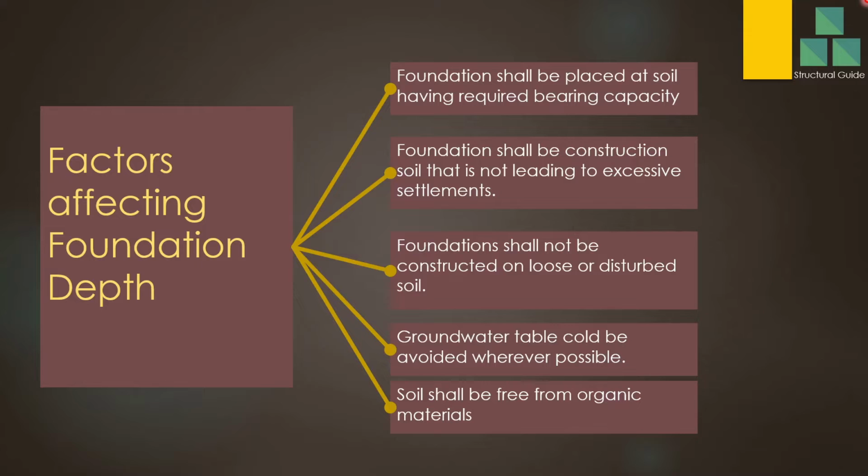Foundation shall not be constructed on loose or disturbed soil. If you are going to have a shallow foundation, you may find loose soil or disturbed soil during the excavation. That soil should be avoided because if you have disturbed soil, when the loads are applied, the foundation may settle. Therefore, that has to be considered during construction.